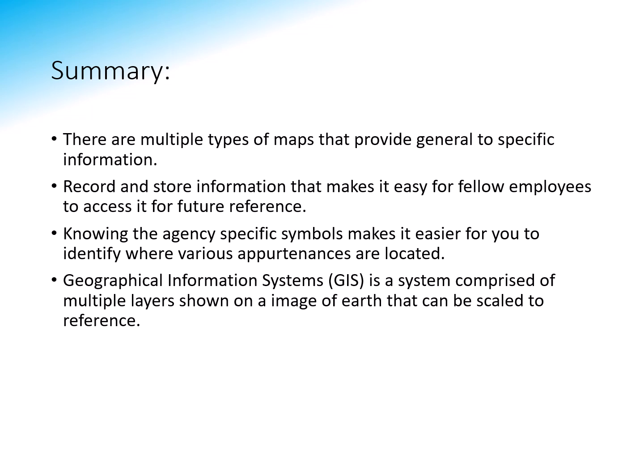Being familiar with symbols is really helpful. You want to know what you're looking at. Knowing how to read stationing is really helpful. And then just having that understanding that there's multiple layers to this, like a GIS system. So if you're not seeing something that you're looking for, maybe that layer isn't turned on. That's something you need to take into consideration.